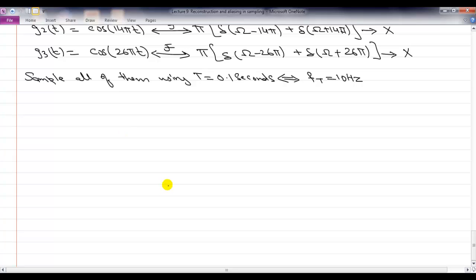If you play with the same figure that I have shown you using one frequency, you will be able to see that there is a very formal relationship as to how frequencies map onto lower frequencies. The right way to think of it is through this aliasing chart.